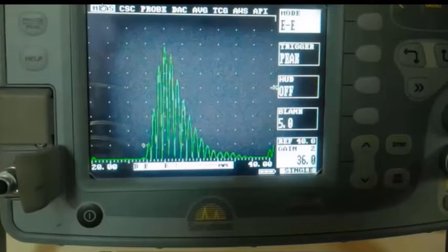So here you can see there is a measurement menu. So now we are actually going to capture the echoes from the sample of known thickness. So here we need something which will indicate what depth this echo is coming at on this screen.